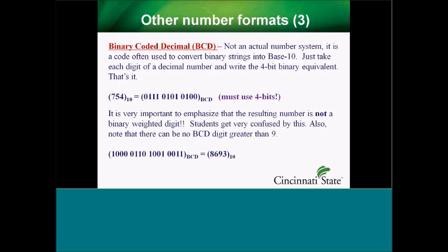And they want a good application of this, which is the 7-segment display that you have in your clock radio. Matter of fact, each one of those segments is a different function of the inputs that it has. So there's a chip, which is a binary to 7-segment display driver. I tell them this is one of the things we have. I give them a homework assignment. They actually have to design the logic for the 7-segment display when we do K-maps. It's kind of a long assignment, but it's a good one.